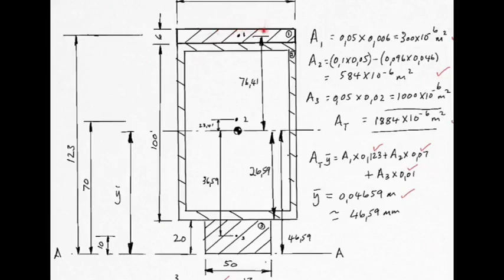That is the one you use with the bending formula, because these fibers are the ones that are furthest from the centroid. These are closer, so they're not going to be the problem. These fibers here are going to see the maximum tensile or compressive stress when this beam is bent or loaded such that it is bent about this axis, which will also be called the neutral axis, by the way, the axis where there's no stress.